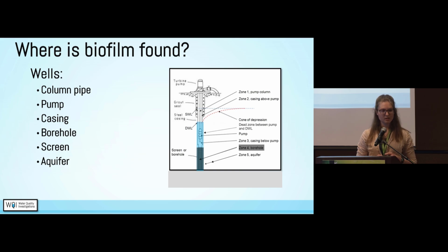One really extreme example we dealt with at WQI was actually a community that was out of compliance with radium. We determined that there was a significant amount of biofilm built up in the borehole of their well, and the bacteria were actually eating away at the borehole materials and releasing that radium. Once we did a really intensive mechanical and chemical cleaning on that well, it was actually brought back into compliance with radium.